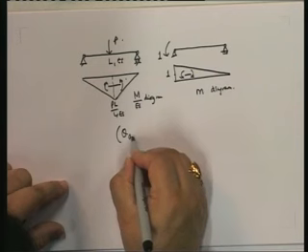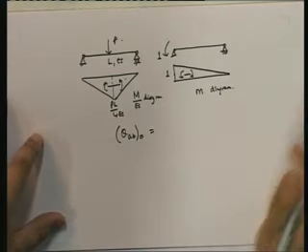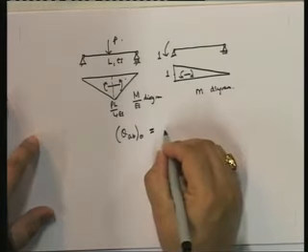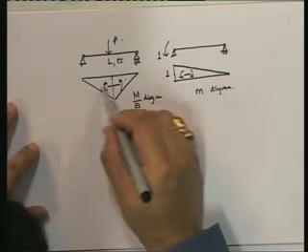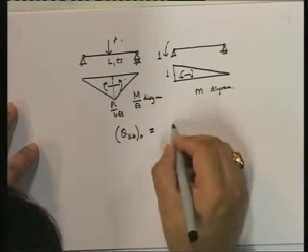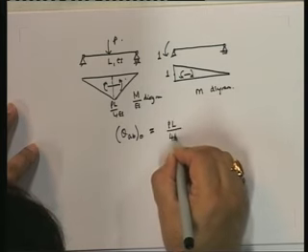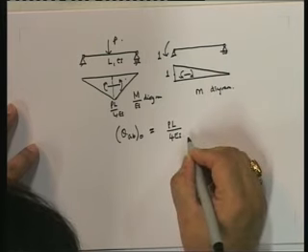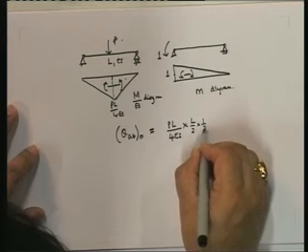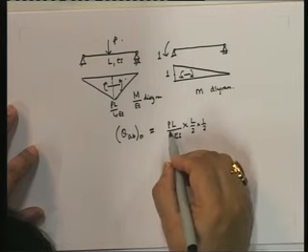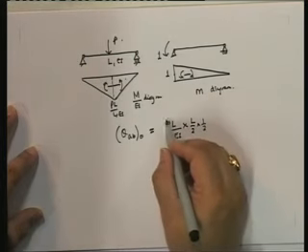So what is theta AB 0 equal to? Theta AB 0 is equal to the area under this curve, so half, because there are two areas, so I have to consider PL upon 4 EI into L by 2 by half length into base. That's the area of the triangle.